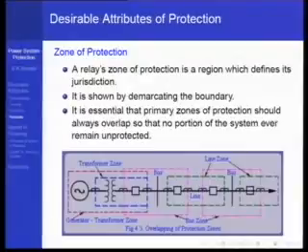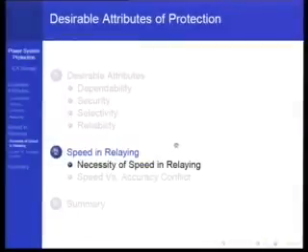The second point, which I have mentioned earlier, is that on paper you will draw very crisp zones, but actual relays may not give you those crisp demarcation boundaries. Distance relays and overcurrents particularly don't give you that kind of crisp demarcation as you show on the figure. So it's good to draw on the figure, this is the zone, that is the zone, but that kind of crispness is not seen unless you use current differential protection, where the CT physical boundaries actually define the zone of the protection. So it's a good concept, but the application of it is, the relays don't per se directly give you a very crisp boundary of protection.